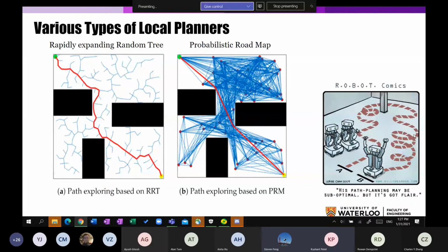So we have different types of local planners. They are categorized into variational, graph search, or incremental search methods. Variational methods make use of calculus to find an optimal motion profile, which can be done by representing the search space, obstacles, and vehicle kinematic constraints, and then formulating it as an optimal control problem.